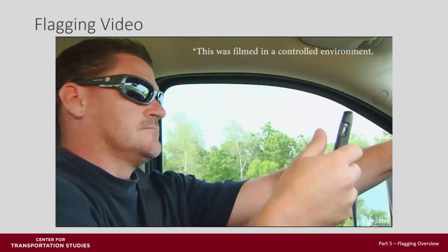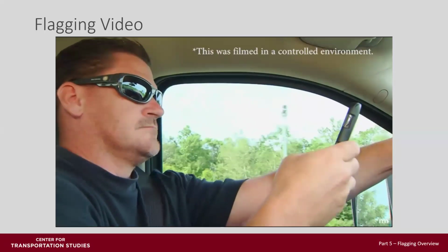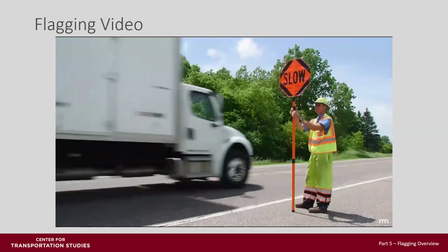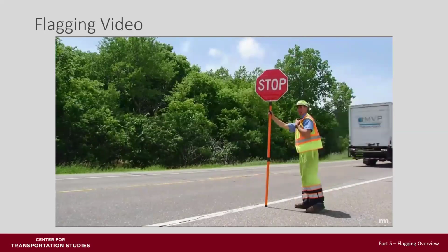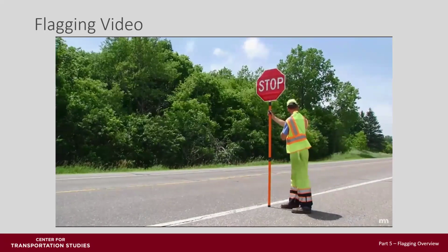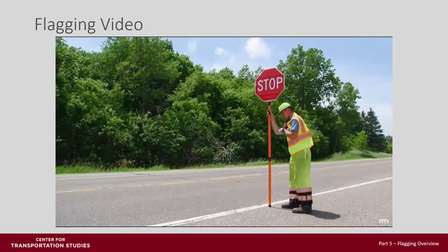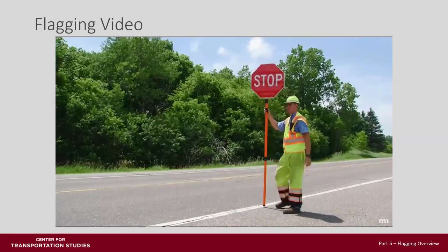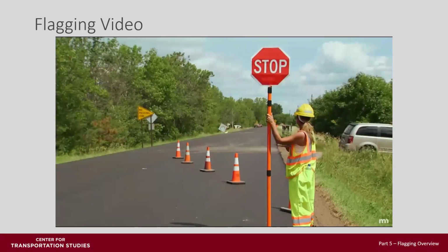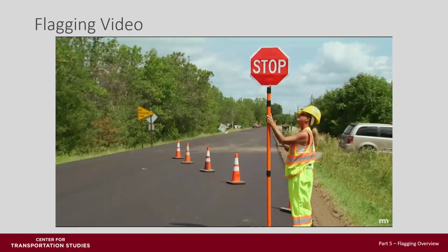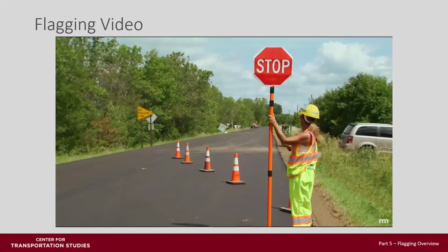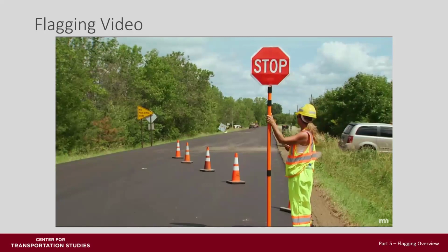Drivers are often tired, inattentive, or impaired, requiring you to remain alert on your feet facing traffic at all times. Never turn your back to oncoming traffic and never stand directly in the path of approaching traffic. Locate your flagging station in a highly visible area. Park your own vehicle off the road away from your flagging station.